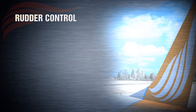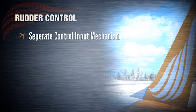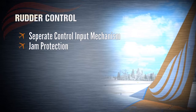Both hydraulic systems and the standby hydraulic system have separate control input mechanisms for the rudder PCU. All three of them have individual jam protection mechanisms. When either system A or B is jammed or disconnected, the main rudder PCU detects a pressure imbalance via the Force Flight Monitor, FFM.